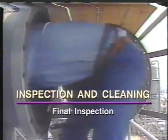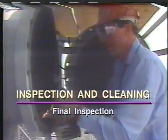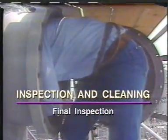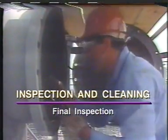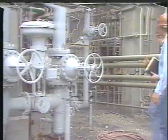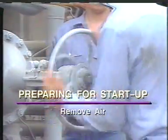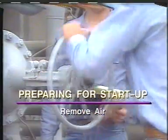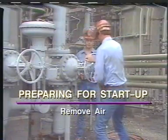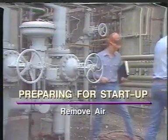After all repairs are made, the tower is given a final check to see that no tools, equipment, or clothing have been accidentally left in the column. A foreign object could plug an outlet after the tower is back on stream, making it necessary to once again shut down the process. After everything is checked and the tower is closed, all air in the column must be removed. This can be done by adding an inert gas like nitrogen or steam to the tower. An oxygen analyzer is then used to verify that no air remains in the system.